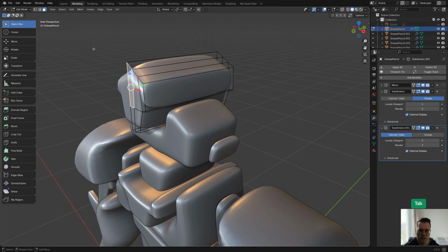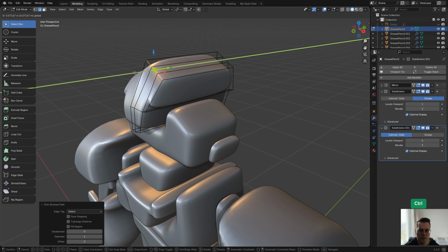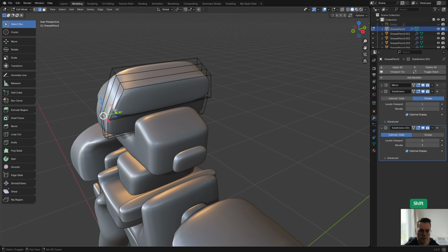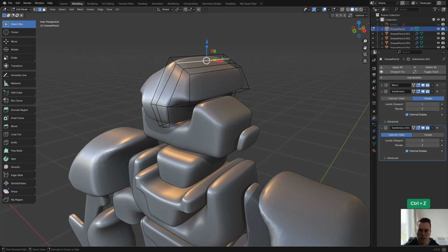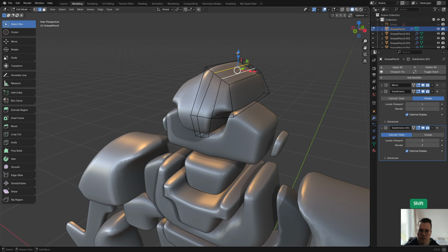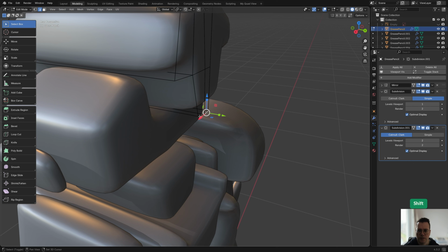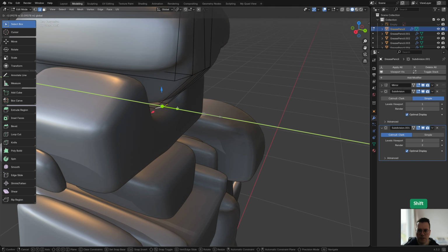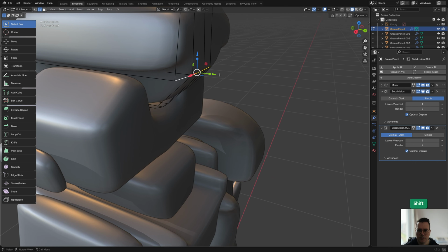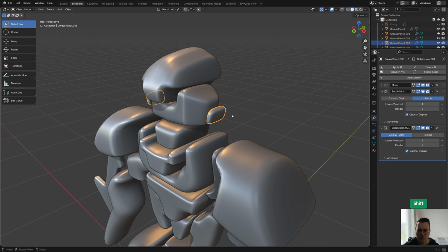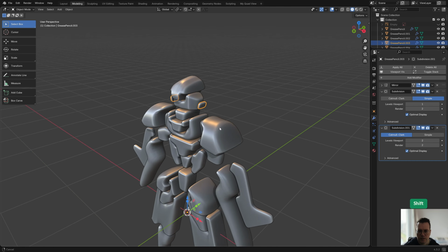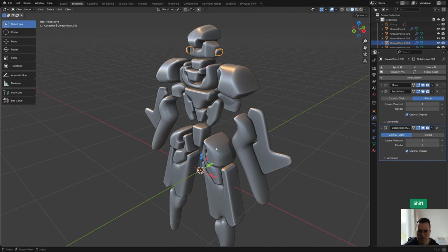So if I select, for example, these edges here, and then we can move these, or we can select these two and move them forward. So that's a very easy way to change the shape. And so because the geometry is so simple, just these small changes make a big difference. So if I want, I can also rotate this object. However, all of the objects have their origin here in the middle now.